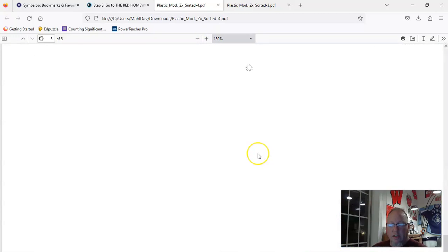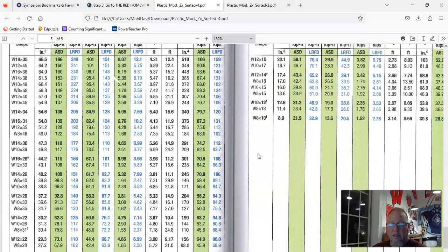So on this chart I need to find 16.2, and I'm just going to go up, and once I find a number that's bigger than 16.2, and remember you should always be looking at the bold numbers, I'm always going to go one bigger. So I'm going to choose this one, 20.1. It's a beam W 12 by 16, and I need this number 20.1 and 103.